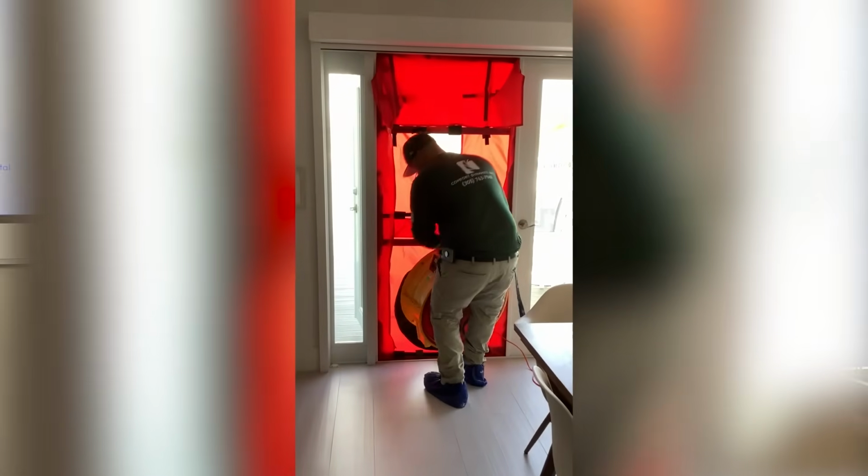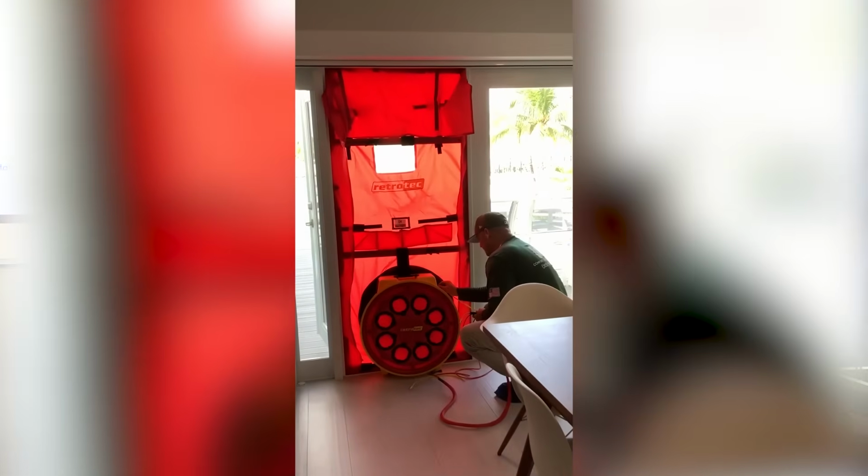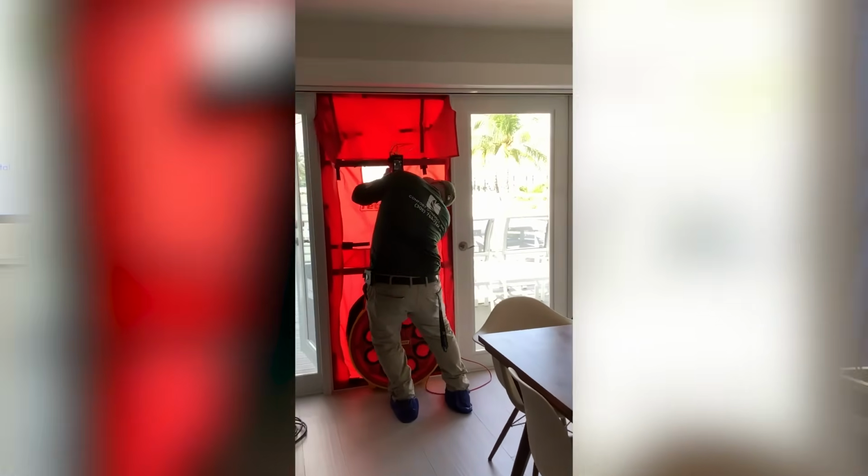door test. Anybody ever seen Max do a blower door test before? Anyone here seen that? So that's when you actually depressurize a house and then you measure the leakage rate of the house. You also will use the Pascal scale when you're doing things like duct leakage or things like that, where you have to measure really, really tiny amounts of pressure.